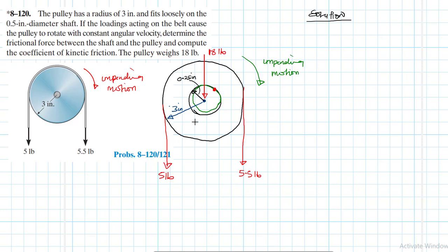All right. So we have this point of contact. This is where the friction force and the normal force will be acting. The resultant of the two, which is R, is always in this direction, which is the vertical direction, like so.